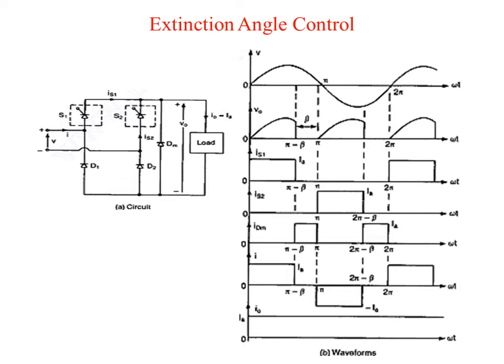The fundamental component of input current leads the input voltage and the power factor is leading. In some applications, this feature may be desirable to simulate capacitive load and to compensate for line voltage drops. Using this circuit diagram, the average output voltage can be found.